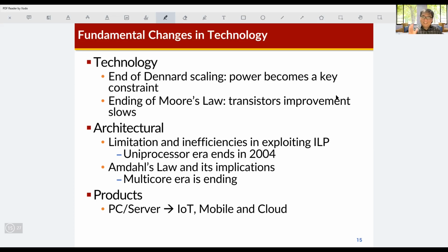But it ends. So that means even though the channel length of the CMOS transistor shrinks, the power consumption does not decrease with the scale of the transistor because of other factors such as the leakage current and some other factors.